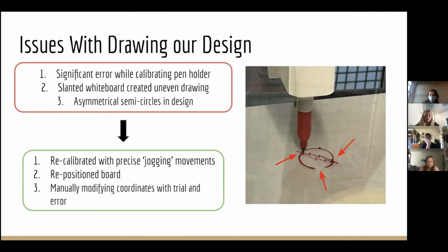To have the robot draw the two semicircles with the Sharpie, we had to modify and store 3 key points. However, we discovered it was difficult to judge whether the points would be equivalent on each side, as we didn't use coordinates, but rather just movements of the robot to visually and mentally calculate where the points should be. This led to the issue of asymmetrical halves, and we had to use multiple attempts at modifying the points.